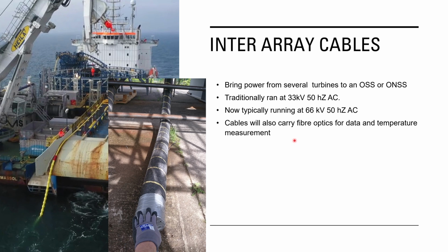So the cable in practice is surrounded by sand, and because all three cores of a three-phase cable are close together, you do get heating from inductive currents. Now that heat has to go somewhere, and it does go into the sand and eventually the sea, but we do need to monitor the temperature of that cable, and we do that with lasers and fiber optics.